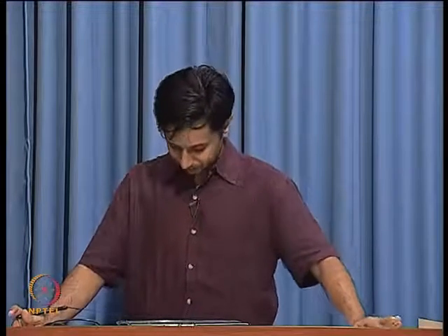Now, common sense, I mean common parlance would tell you that probably a low noise amplifier throws out the noise and keeps the signal. No, you can't throw out the noise. Once there is noise in the system, it cannot be rejected, right. So, therefore, a low noise amplifier cannot throw out the noise and keep the signal. It has to handle both the noise and the signal that it has already received.